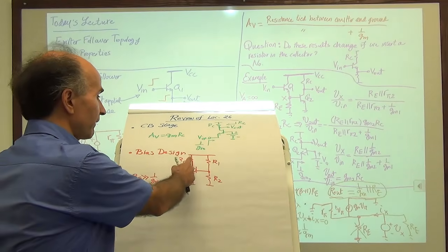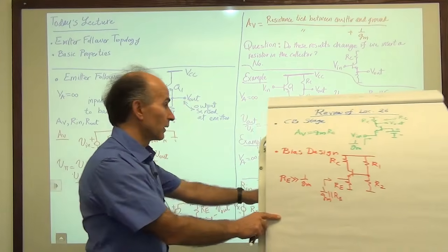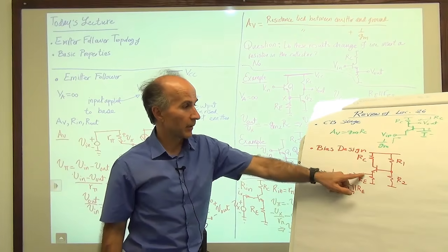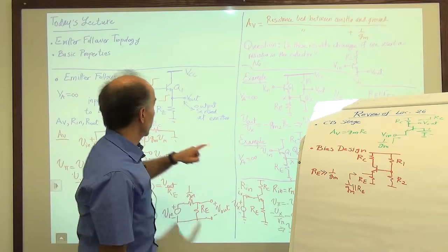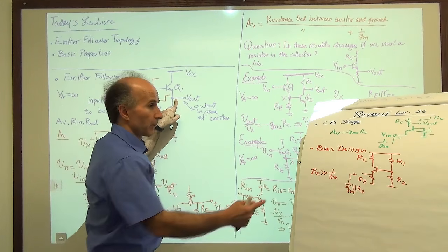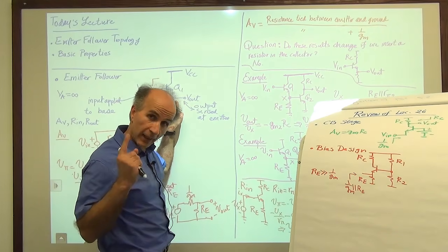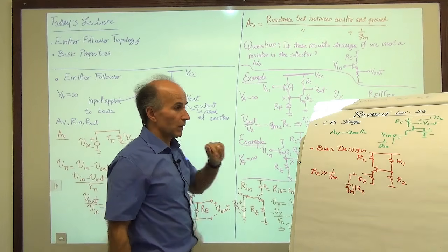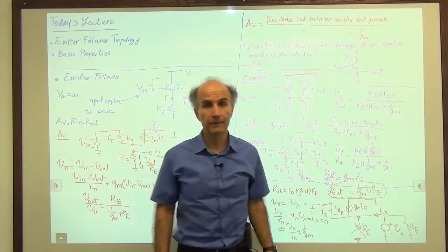Because remember we said having an RC here or not doesn't make any difference, right? So whether we have this circuit as a common base stage and we are sitting here and looking into the emitter, or whether we have this circuit and looking into the emitter, we should see the same thing, because this resistor doesn't play a role in what the circuit does, as long as early effect is neglected.